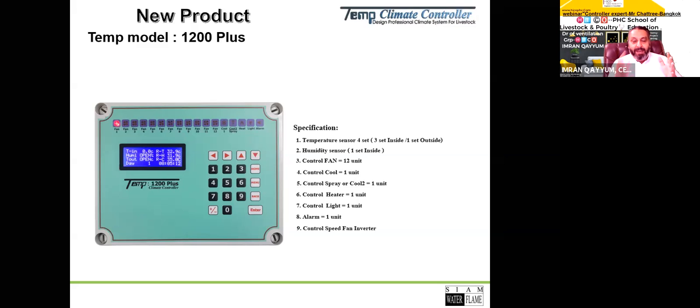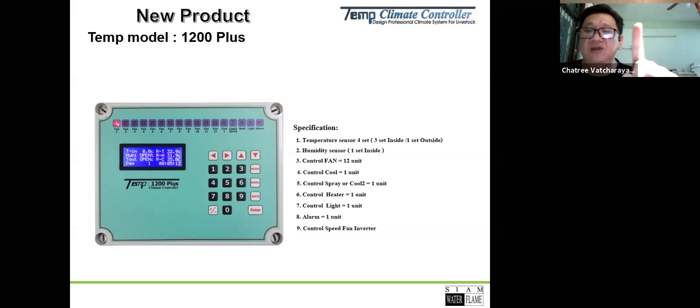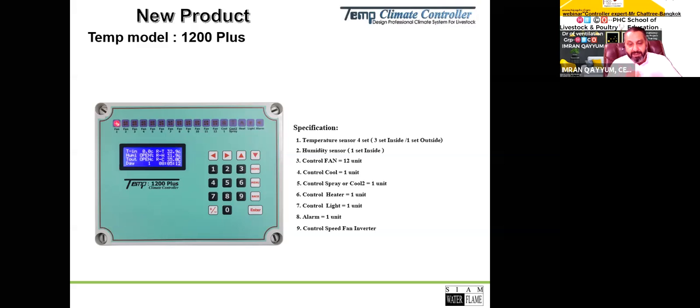What do you suggest, which one is better? The inlet opening percentage, or your inlet controlled on the static pressure which you fixed? If you have a target of 25 Pascal, your inlet will be open only 20, and for me, close on 25 Pascal.